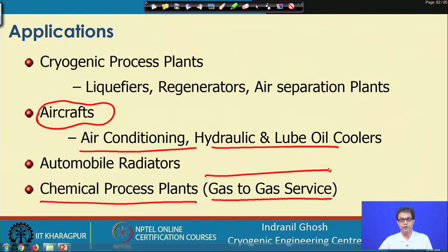If any kind of dirt or contamination is there in the process stream, you will find that those flow passages get choked, and if anything such happens, often it is not possible to clean it if it is not getting dissolved through some chemicals.